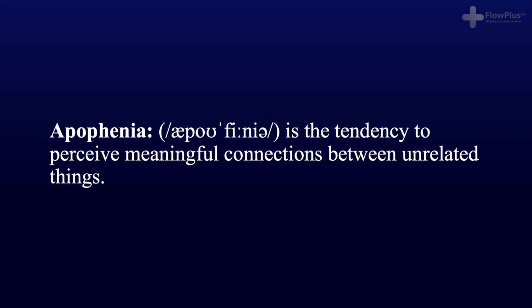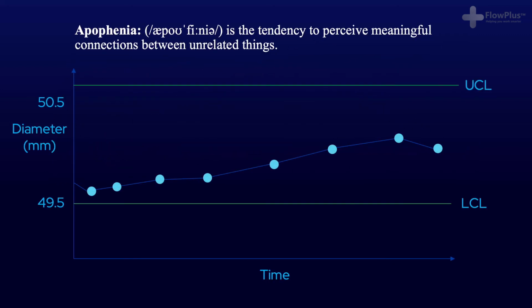For example, if there are 6 consecutive increases in a row, an operator may see this and change the machine settings, with the prediction that the process will soon be out of control. By changing these settings, the operator has reacted to common cause variation and caused a change in machine conditions. This random common cause variation means the process is in control and doesn't need any adjustment or action. By changing the settings, this can cause the process to become out of control.